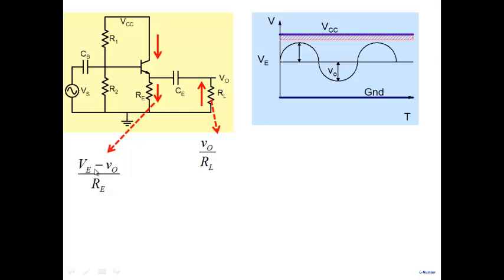When I want the maximum current in my load here, this current is minimum. So this is the problem with this particular circuit here. As I'm building up my voltage swing here, I require higher and higher current. And on the other hand, the capability of this side becomes lower and lower. The current handling capability of this one here keeps on falling.